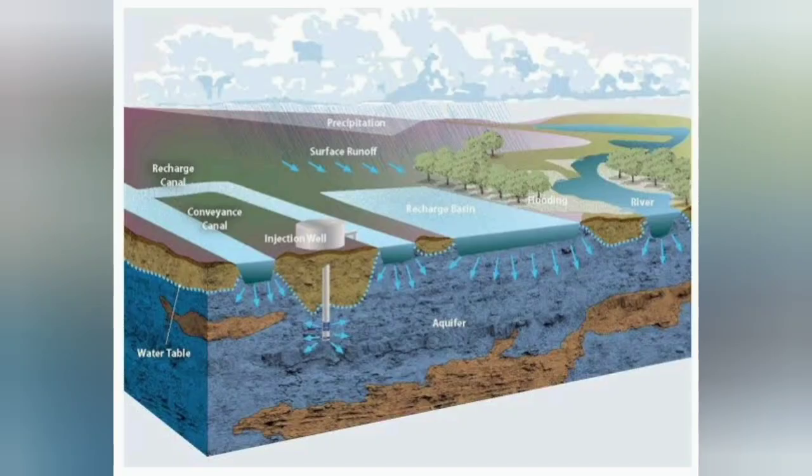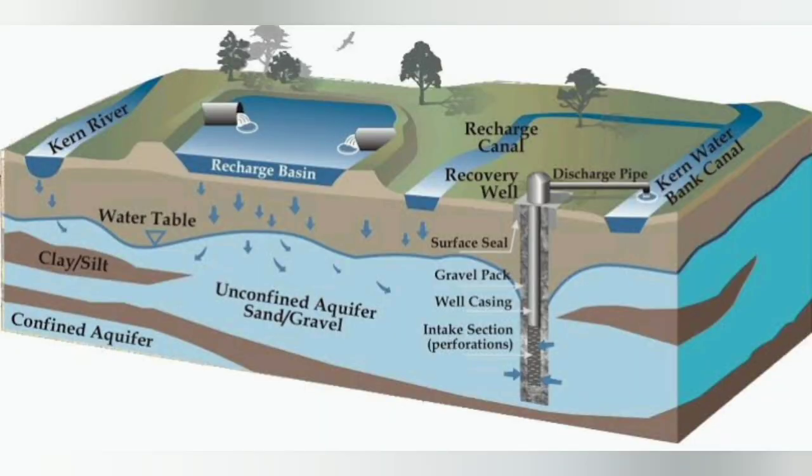So, we will discuss the basic requirements for artificial recharge projects. That means, if you are planning for any artificial recharge techniques, then what you should have is availability of non-committed surplus monsoon runoff in space and time. That means that particular location should have more surface runoff during the monsoon seasons.